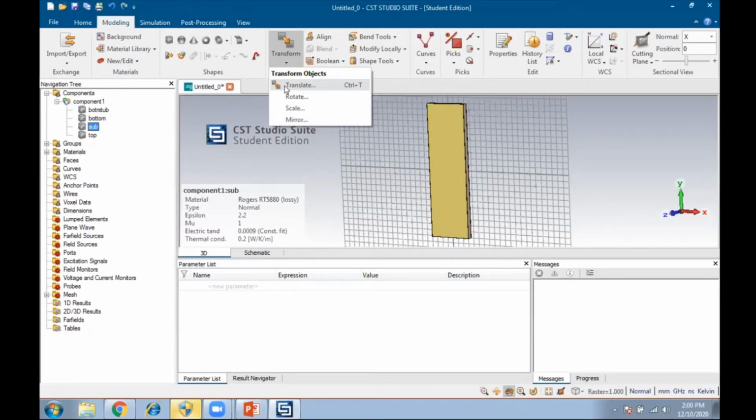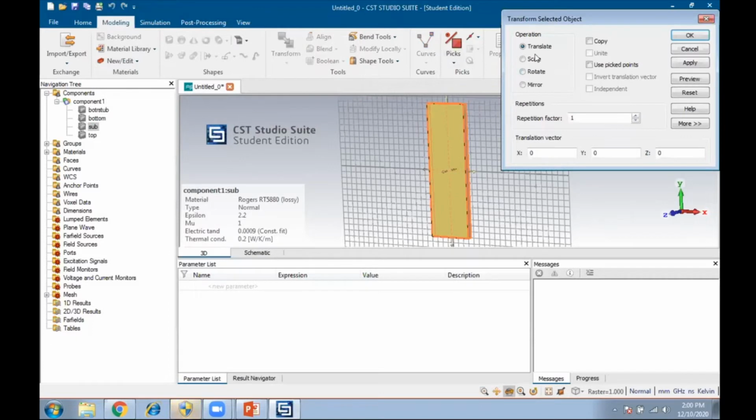The spacing between the two stubs is the translate. Need to give here a copy. In which axis do you need to copy the stubs? In the y-axis. So what is the pitch? That is the spacing between the two stubs I already gave in the PPT for design consideration of the stub. That is actually 1.2, right?